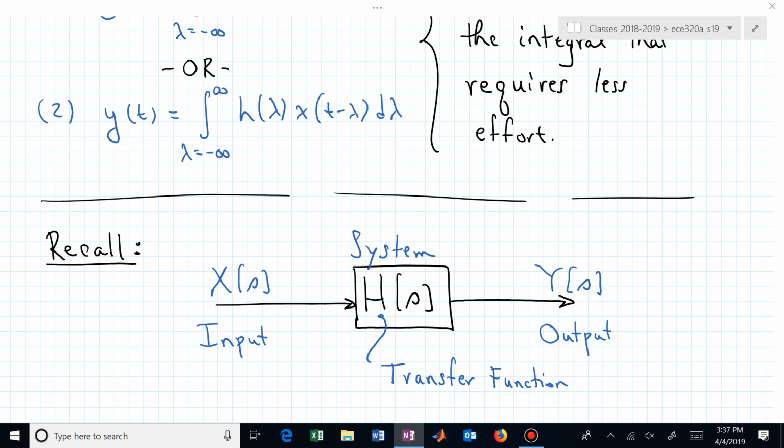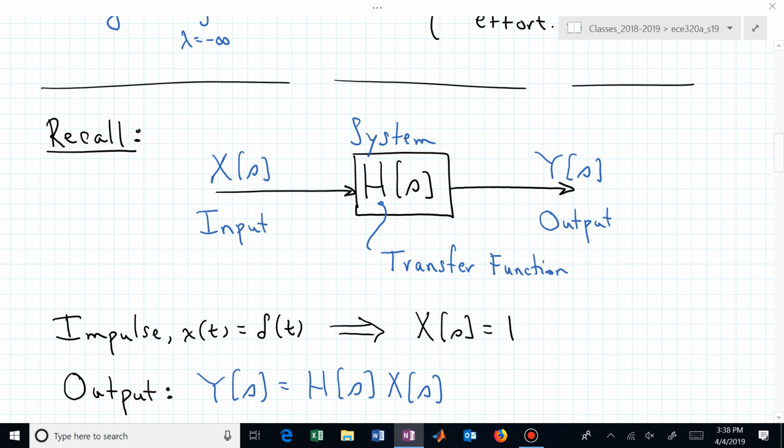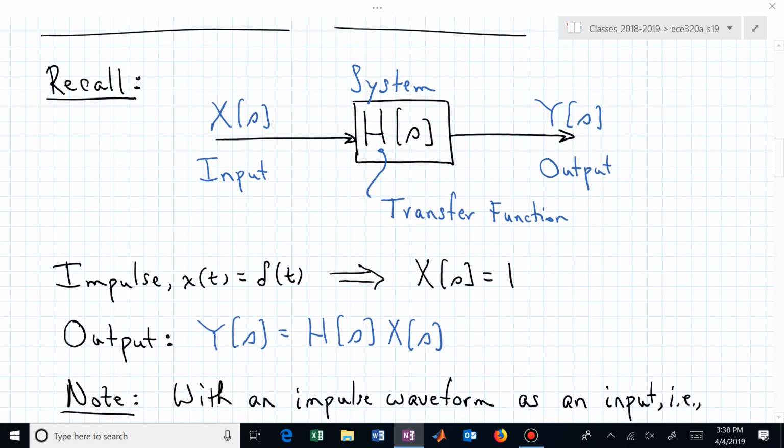That's the block diagram description. And in later courses, you'll need to be very comfortable with this concept of a transfer function. And that carries over into multiple domains, not just electrical and computer engineering. What we want to do is think about that process not only in the frequency domain. In the frequency domain, the output Y of s is simply equal to H of s times capital X of s.